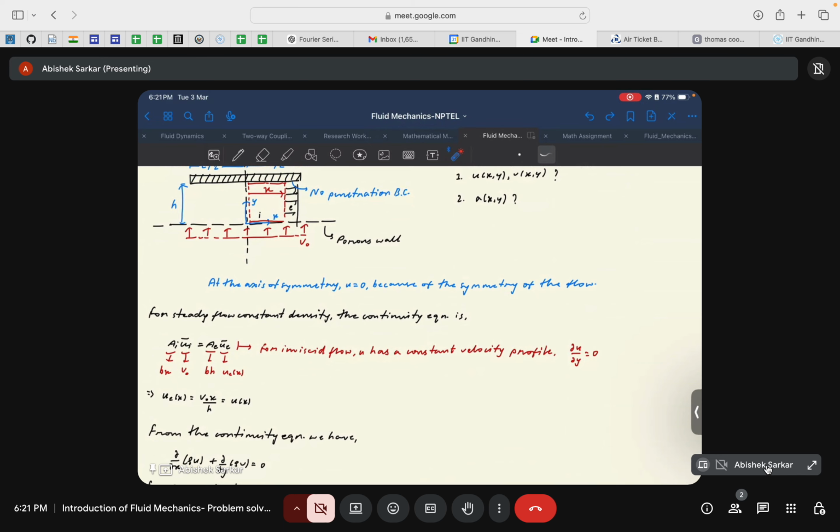And if there is a problem that is related to finding the force, the net force acting on the control volume, for those kinds of problems the equation of interest becomes your momentum equation, because it gives us the rate of change of momentum, which is basically the force acting on the body. Okay, and you will see that these two equations are not explicit, rather they are interrelated, where to find the unknown parameters for the momentum equation, you will have to explicitly solve the continuity equation.